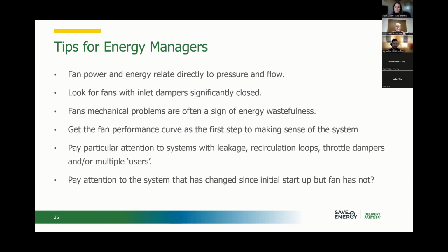One thing I want to mention, and this is an opportunity that I've seen many, many times, is when somebody has designed a system where the fans have multiple users. By multiple users, I'm not talking about a person, I'm talking about a different aspect of a process. But it's being asked to deliver air to this part of a process and that part of a process. Well, not all these processes may need the same amount of pressure. If you don't need the same amount of pressure, guess what the fan has to do? The fan has to crank up the pressure to supply the part of the process that needs the most pressure. That's what it has to do.